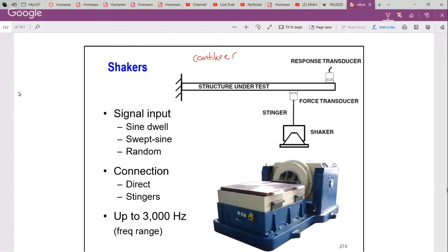The power amplifier takes a low-level signal from your phone or whatever source, hopefully doesn't modify it because its frequency response is flat over the range of frequencies you're going to be listening to music in, and then it provides a significant signal output that looks exactly like the input except higher voltage and more current capacity, which means the speaker, the actuator, can pull a lot more current from that without distortion.